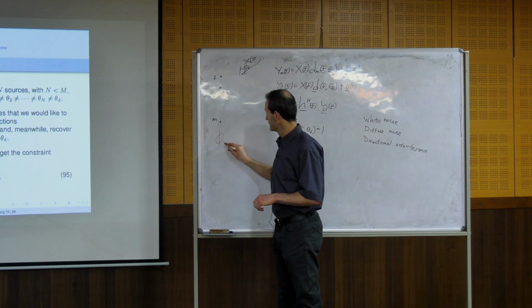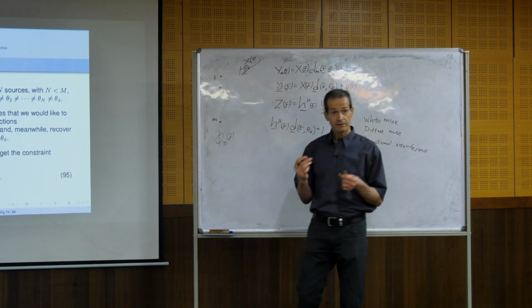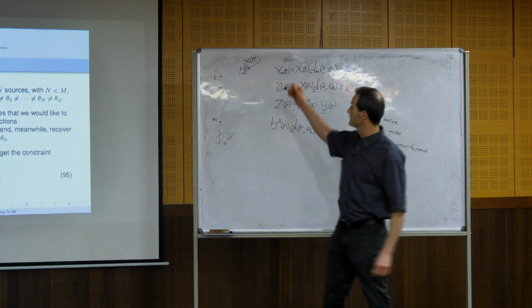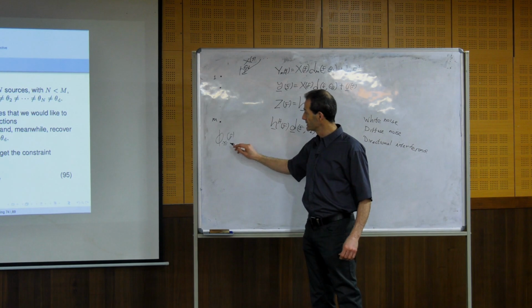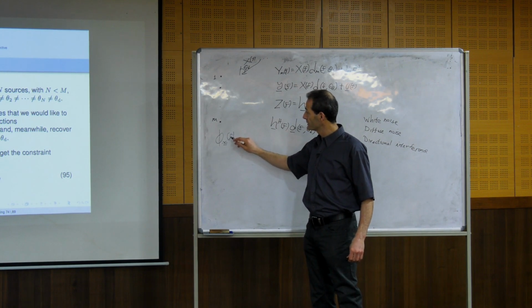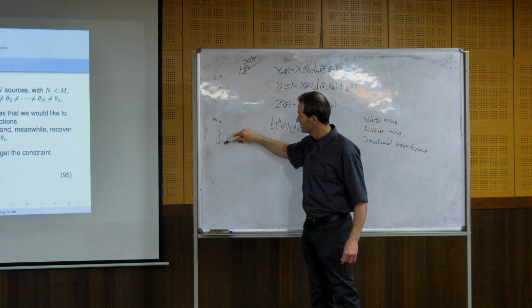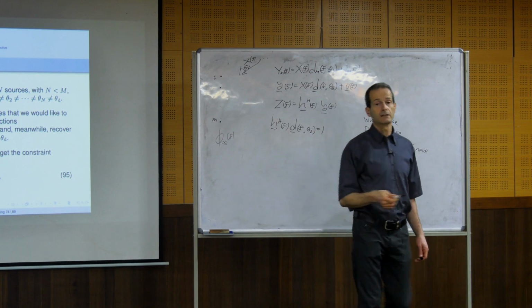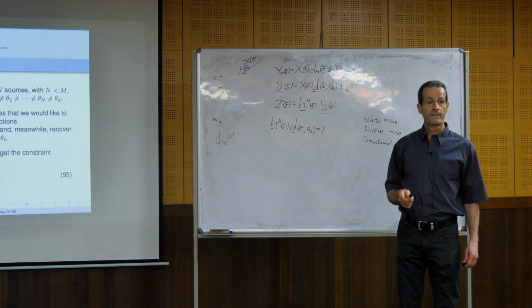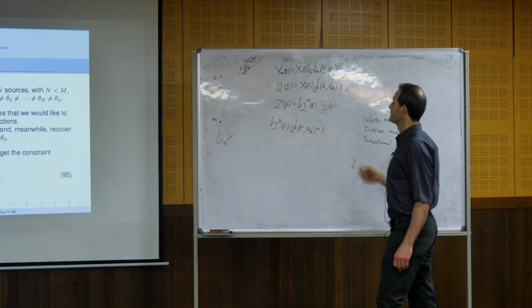phi x of f. This contains information about the specific characteristics of the signal that comes from theta d. And then we have certain correlations that take into account the correlation between the desired signal component in a certain sensor and another sensor, for example the reference sensor. Okay? So this is important information that we don't know.